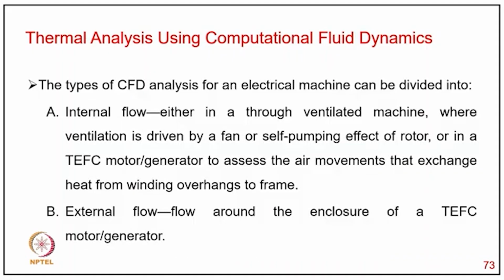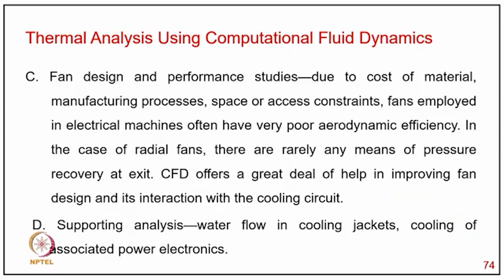The types of CFD analysis for electrical machines can be divided into parts. A, internal flow, either in through-ventilated machines where the ventilation is driven by a fan or the self-pumping effect of the rotor, or in a totally enclosed fan cooled motor generator, to assess the air movement that exchanges heat with the winding overhangs and the frame. And B, the external flow around the enclosure of a TEFC motor generator.